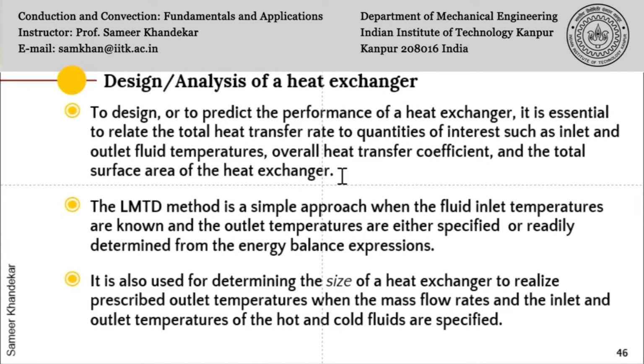So for such type of problems, as we said, the LMTD method is a simple approach when the fluid inlet temperatures are known and the outlet temperatures are either specified by the client or readily determined from energy balance expressions. So when the inlet temperatures and the outlet temperatures, or the expected outlet temperature, are specified, then we will use, as I said, the LMTD or logarithmic mean temperature difference method for this class of problems, the sizing problem.